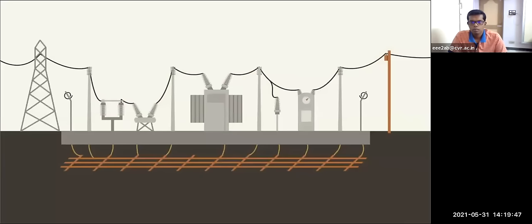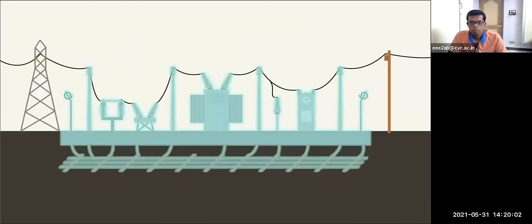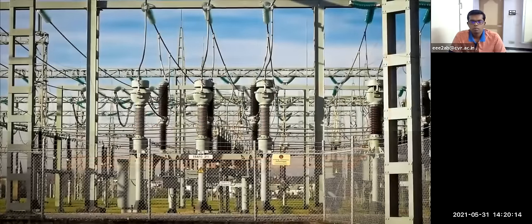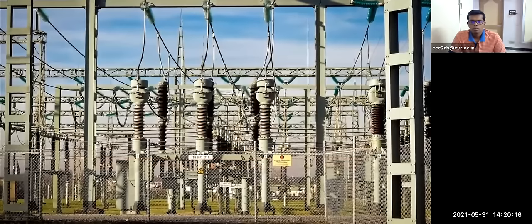All substations are built with a grid of grounding rods and conductors buried below the surface. In the event of a fault, the substation needs to be able to sink lots of current into the ground to trip the breakers as quickly as possible. The grounded grid also makes sure that the entire substation and all its equipment are kept at the same voltage level, called an equipotential, so that touching any piece of equipment doesn't create a flow of electricity through a person. Finally, substations are surrounded by large fences and warning signs to make absolutely sure that any wayward citizens know to stay out.